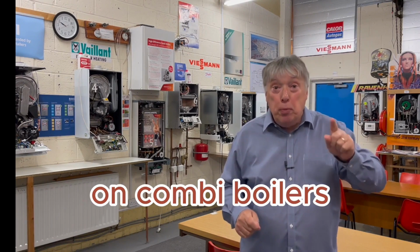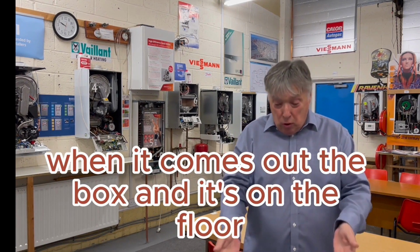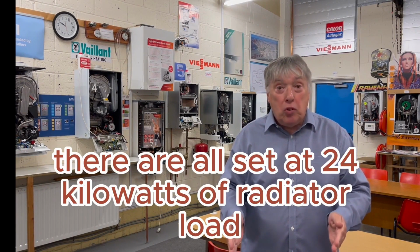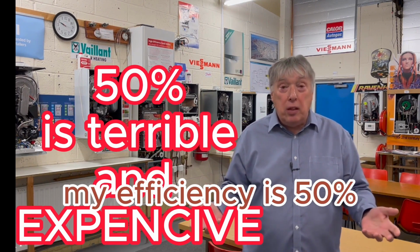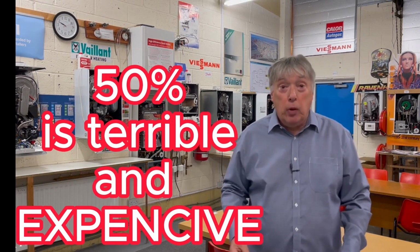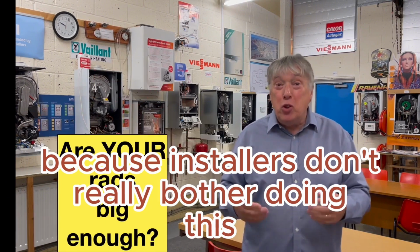Because we know on Combi boilers, a lot of them, in fact most of them, can be range rated. When it comes out the box and it's on the floor, they are all set at 24 kilowatts of radiator load. But as you can see here, I've only got 12. So therefore, my efficiency is 50%. And if I did nothing, my gas bill would be twice the amount. And that happens all over the UK because installers don't really bother doing this.